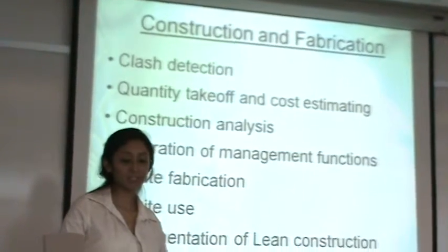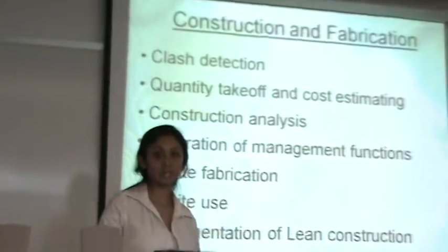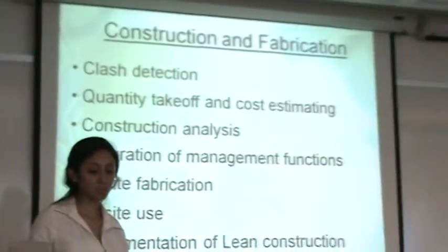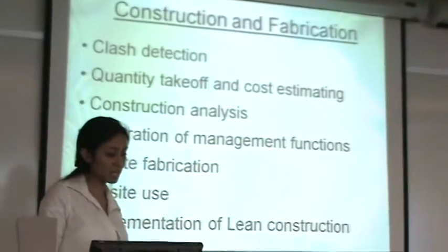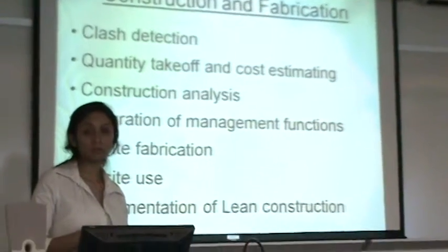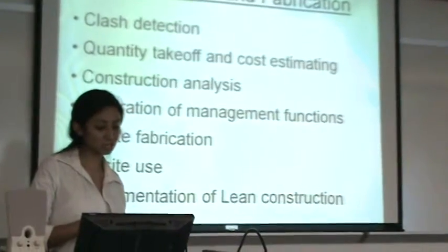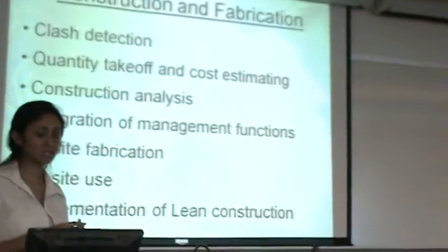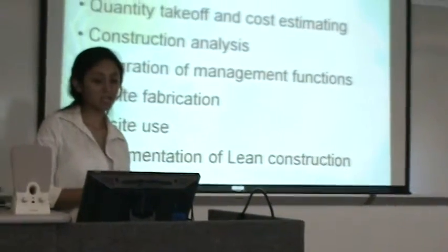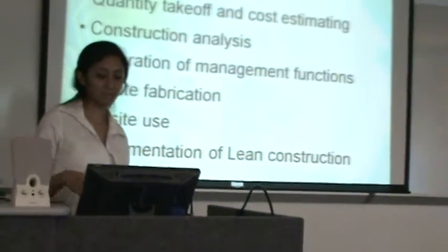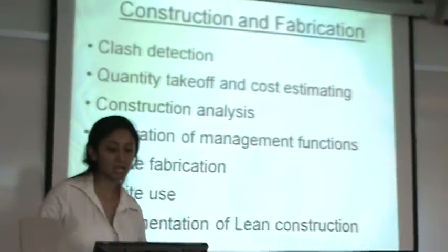BIM can also help in construction and fabrication. This is through the use of clash detection tools, quantity takeoff and cost estimating, construction analysis, through the incorporation of BIM components and construction method information, including spatial, resource utilization, and productivity information. The 4D CAD also comes into play when you have construction analysis.